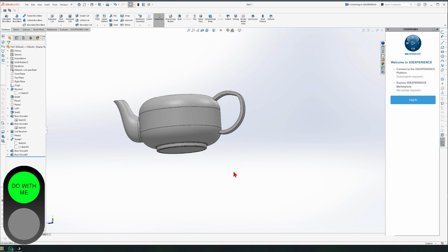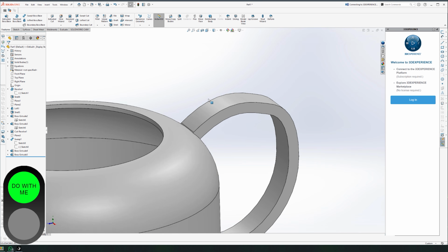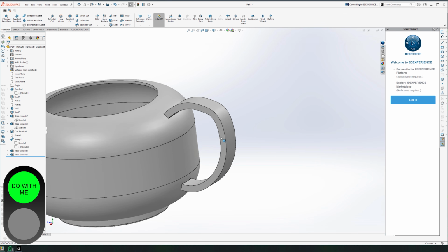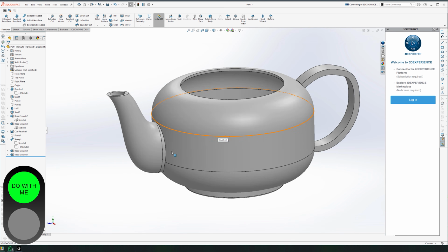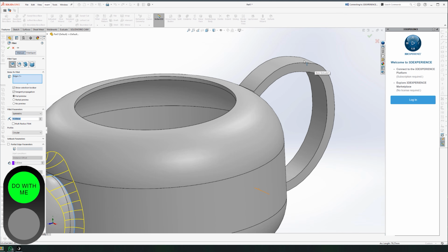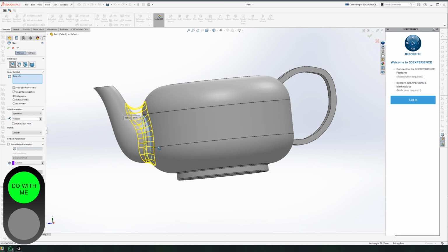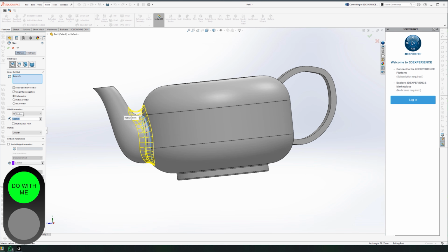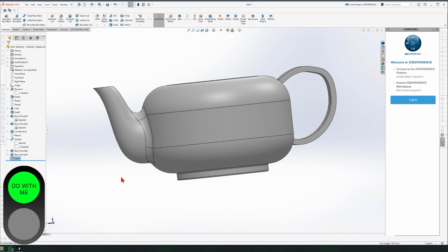No issues. All good. Now, so many sharp edges that we need to round using Fillet. For example, select this line, go to Fillet. If your handle is not like mine, it's fine. But I hope at this point we are all dealing with the same thing over here. Let's go with 7. 7 is fine, guys. And click OK.